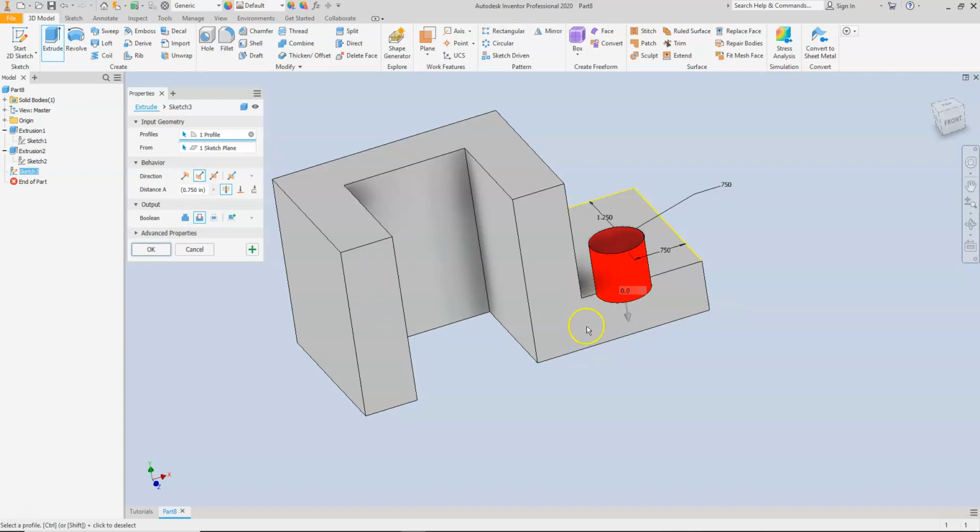If you were to go back and change the depth of this in a particular sketch, it's always going to cut through that surface. So that is a good practice to get into, especially if you know that the part you're designing is always going to have a hole that goes through it. If it's going to be made up with something, then you may not need to go all the way through. But if you're going to put a bolt through something, you want to always have a hole there. You're never going to have to go back and change the length. So I like to use through all.